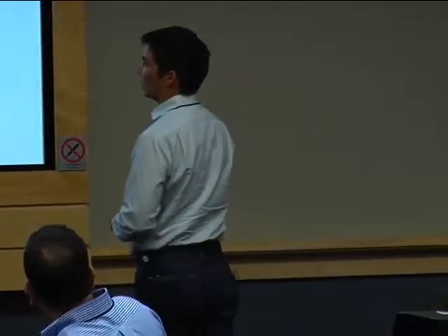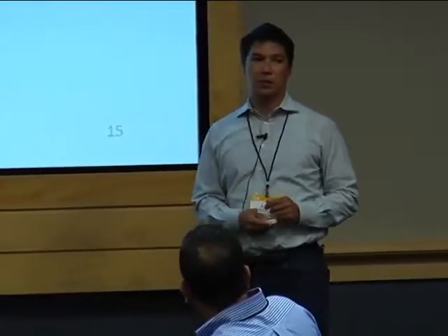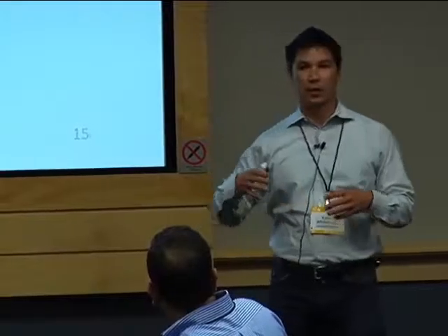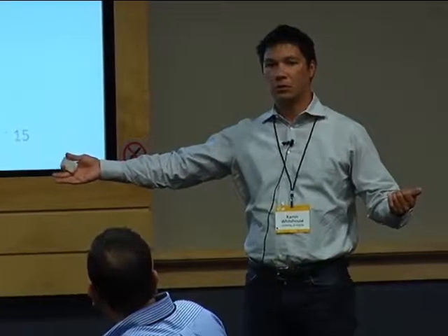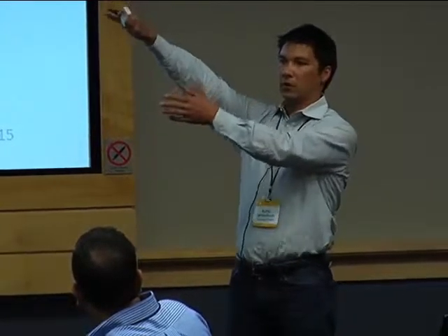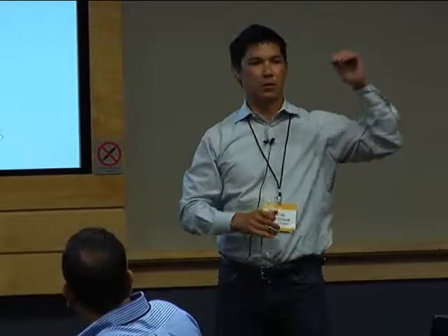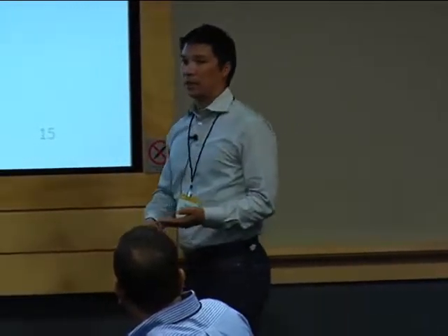We also found that even if we did want to use these receptacles, we often had to run long wires. You don't have power, for example, in the middle of the wall or top of the door or the top of a window, in the places where you want to deploy your sensors. In one house, we had over 250 feet of wire just to power 13 sensors. Running these wires is very costly, of course.